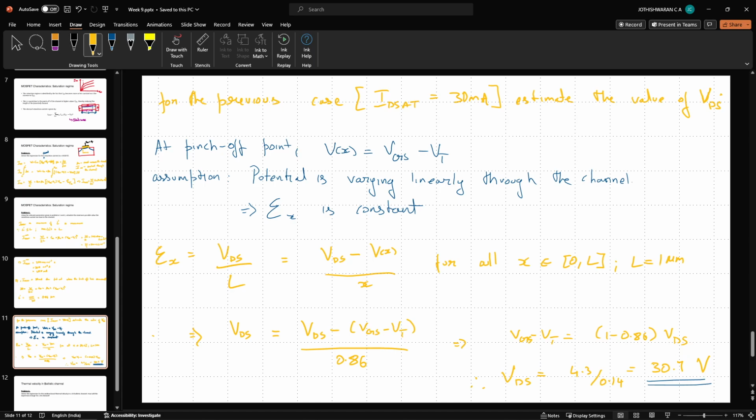So this is the idea of saturation. In the linear regime, had I doubled the voltage, the current should have doubled. And up until 25.8 milliampere, that will happen more or less. But going from 25.8 to 30, which is a very small increase, the increase in VDS is going to be significantly large. So that is the idea of saturation. This entire problem was done to show how the voltages and currents vary in a classical MOSFET.